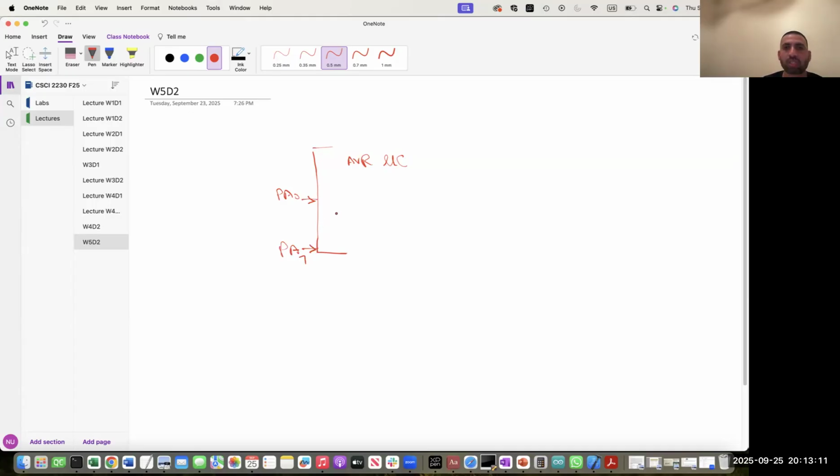So the port is configured. Now the signals of whatever input you are placing on these pins are internally stored in a logic circuit, and it takes one clock cycle for these input ports to be latched in this logic circuit. So it takes one clock cycle, right?